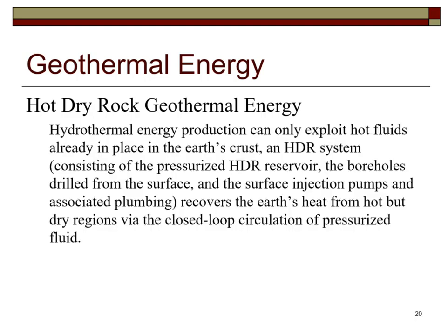Hydrothermal energy production can only exploit hot fluids already in place in the Earth's crust. A HDR system, consisting of the pressurized HDR reservoir, the boreholes drilled from the surface, and the surface injection pumps and associated plumbing, recovers the Earth's heat from the hot but dry regions via the closed-loop circulation of pressurized fluid.